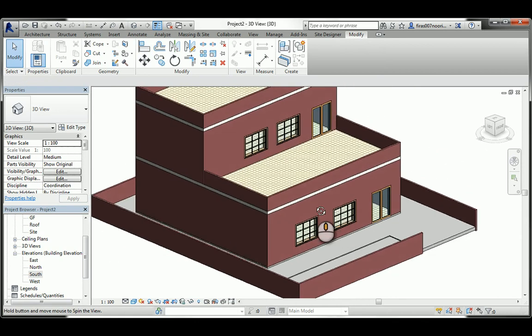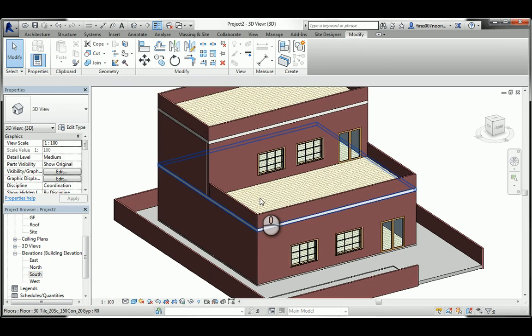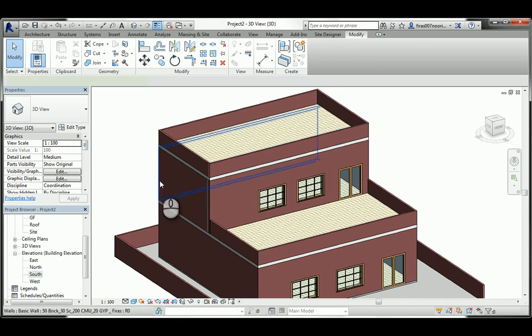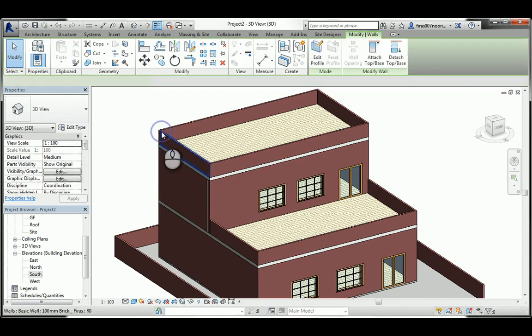So in this lecture we learned more about multiple layer, or complex walls, and monolithic walls, which are walls that have a single material, and both are actually physical or material based walls. Same thing with the slabs, and we learned how to make walkways and how we control their height, how to make a garden, how to make fences, and how to understand the difference between the core center and the wall center, and the need to create the parapet facing the external face.